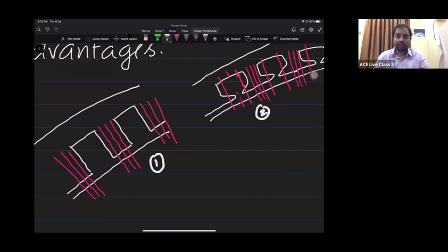The harmonics are going to be minimized, and noise and vibrations are going to be reduced. So this is one of the advantages we are having with semi-closed slots compared to open slots. As the slots are partially closed, the flux lines are uniformly distributed, even coming in the slot region also. As a result, the flux distribution will be merely uniform. Is this point clear? Confirm me.